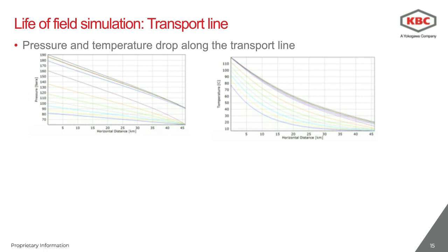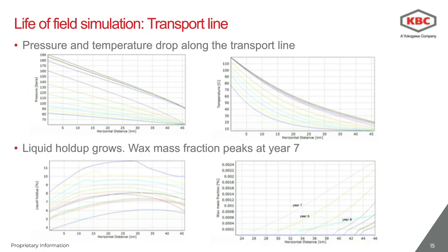Perhaps I need to go a bit deeper into the investigation of the properties of the simulation of the flow to look at what's going on. And I can plot, for instance, the profile for the liquid holdup. On the left-hand side here, you can see the liquid holdup along the flow line. As one would expect, as the temperature drops and the composition of the flow varies, the liquid holdup increases.